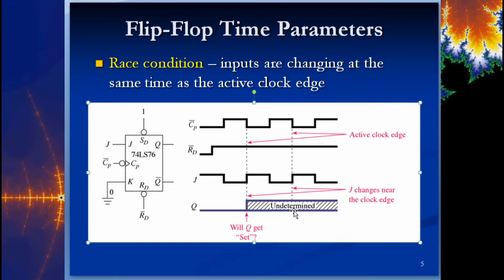Unless you run your simulation a lot of times and try to do it in real time, you really don't know how Q is going to operate. Maybe it accepts it as a 1, maybe it doesn't. Maybe it didn't transition fast enough and it read it as a 0, 0 and kept it in a hold. Or maybe it did transition quick enough and you now have a set. That's why you see both sets of lines here: the set line and also the reset line.